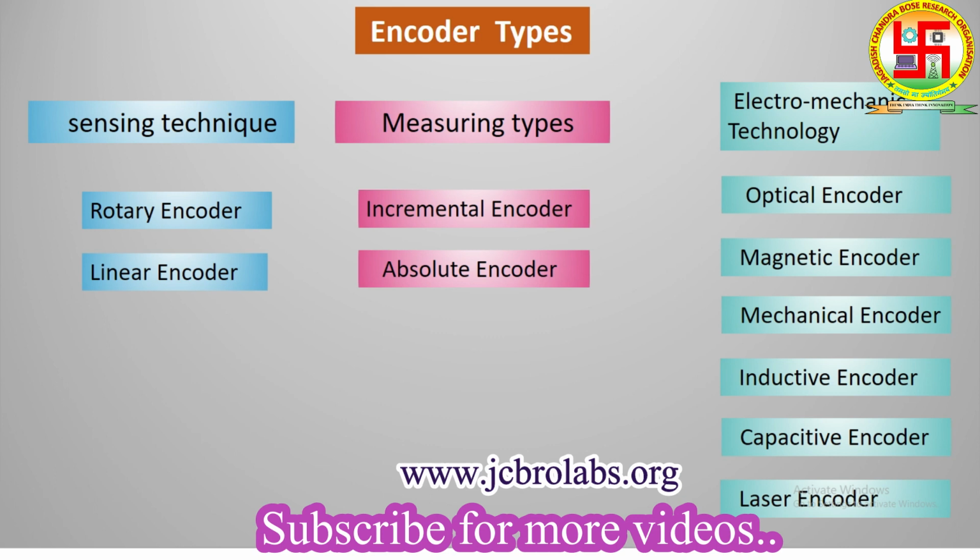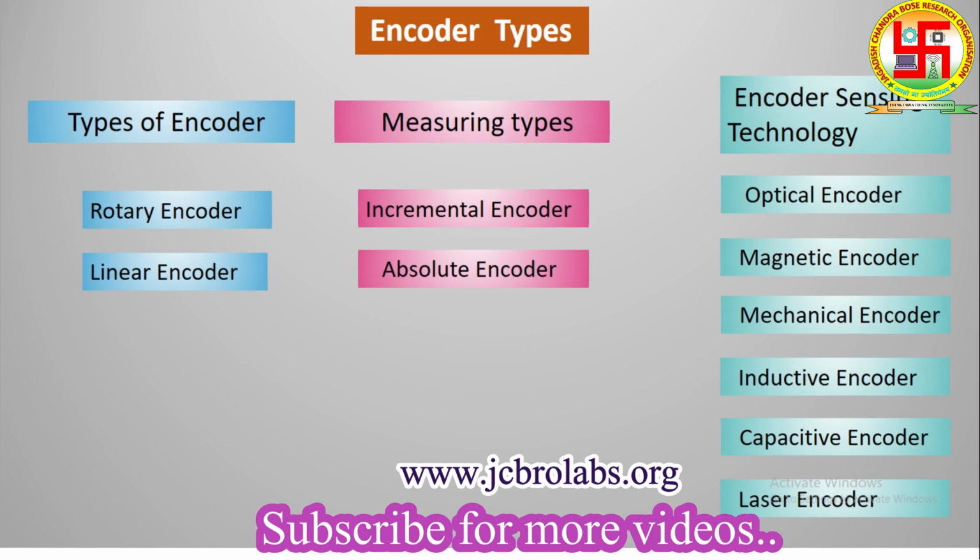Now there are different types of encoders. Based on type, there can be rotary encoders and linear encoders. Both rotary and linear encoders can be of the incremental or absolute type. Then there are sensing technologies: optical, magnetic, mechanical, inductive, capacitive, or laser encoders. Here we will deal with optical encoders only. The principle is very easy for the optical encoder, and otherwise the entire working is the same for different kinds of encoders as well.